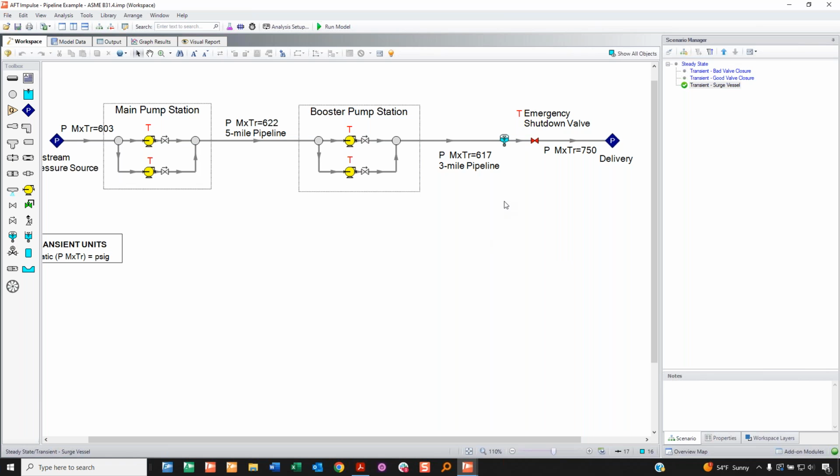Relief valves, well, I guess that's more for process, like in a processing plant or something like that, you discharge to a header or something like that. But there's other mitigation methods and prevention tools, which is what the code talks about, right? Make sure you have components to help with surge. That could be the surge vessel, that could be better valve operation, that could be an air valve we have here, that could be a relief valve, that could be another type of control valve and open up to another line. Many ways you can test helping the surge that happens.